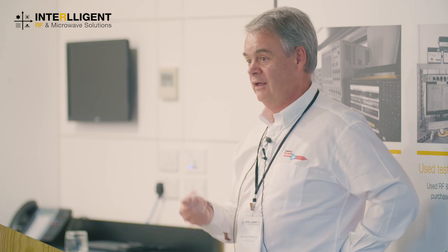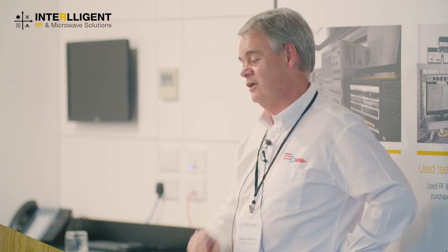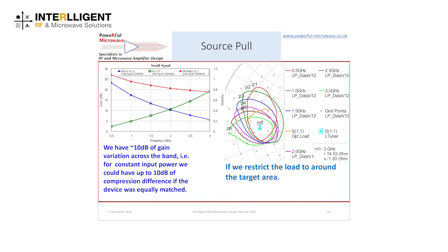And when you're talking about a power amplifier, throwing away gain isn't always as easy, because if your drive level is 2 watts maximum on your input, that means that's 2 watts of power you've got to somehow dissipate. So you've got to have components that are rated as handling that. As I said, if you're using a balanced design, it's not such an issue because you can reflect that back into the quad hybrid and then into the load of the quad hybrid and dissipate it there, and it's fairly easy to dissipate on that resistor.